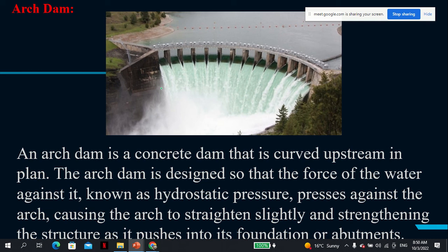This is the same idea as with pre-stressed concrete, right? You provide some pre-stress, and in service you apply a positive stress, because the pre-stress is negative. The positive stress applied in service cancels out the negative stress that was already applied inside the concrete. And so, for all intents and purposes, the concrete in its lifetime is carrying loads, but the net stress is close to zero. It feels like it's experiencing zero stress, and this controls deflections and also ensures serviceability of your concrete structure.